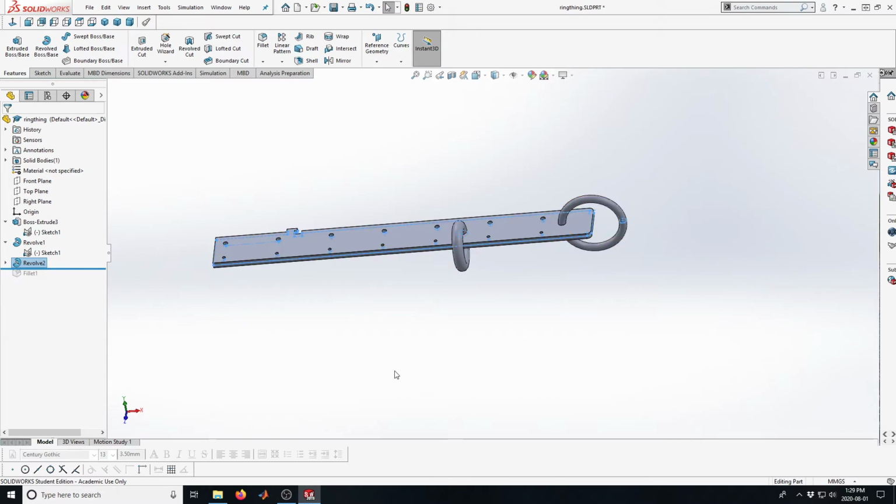So that's my quick summary of what we've done. Everything is sketch driven, and the feature tree tells you what's going on. The shorter the feature tree, the more robust the model. And that's what I've seen over the years in terms of lots of different CAD models. The more you can embed in terms of detail and design configuration in the initial sketch, the more robust the model will be as well. So keep that in mind.